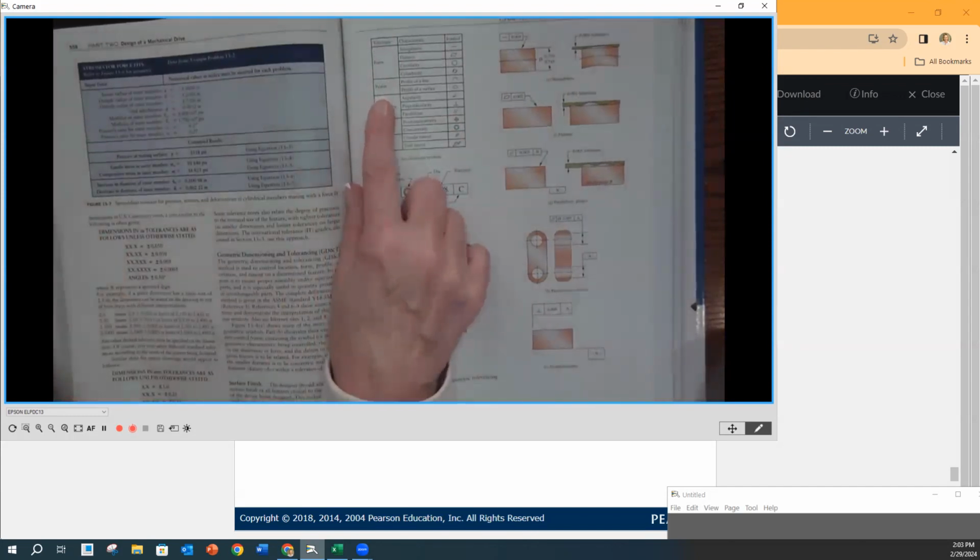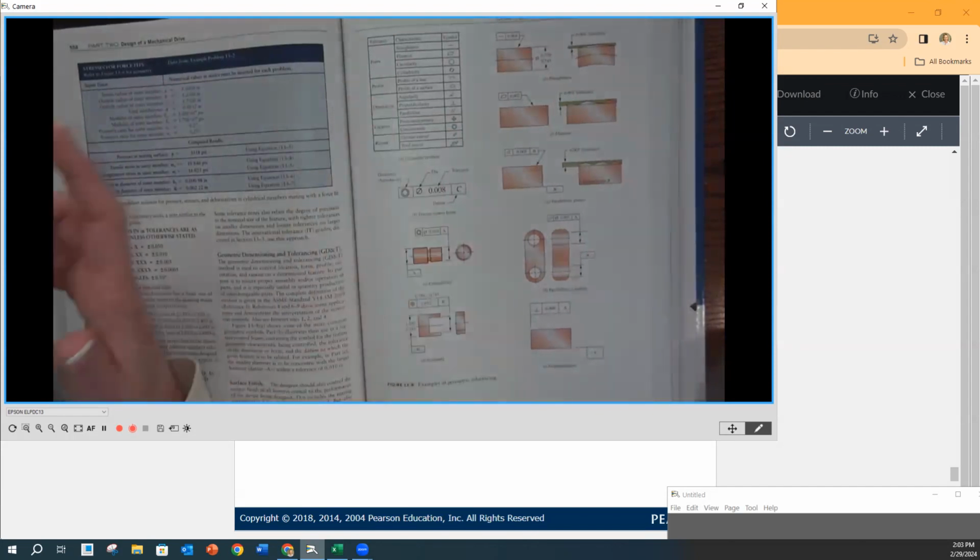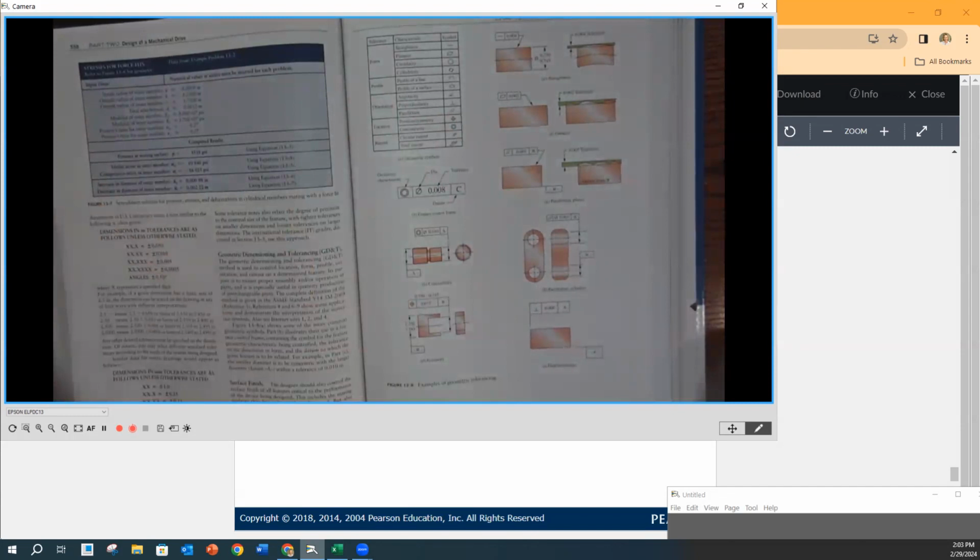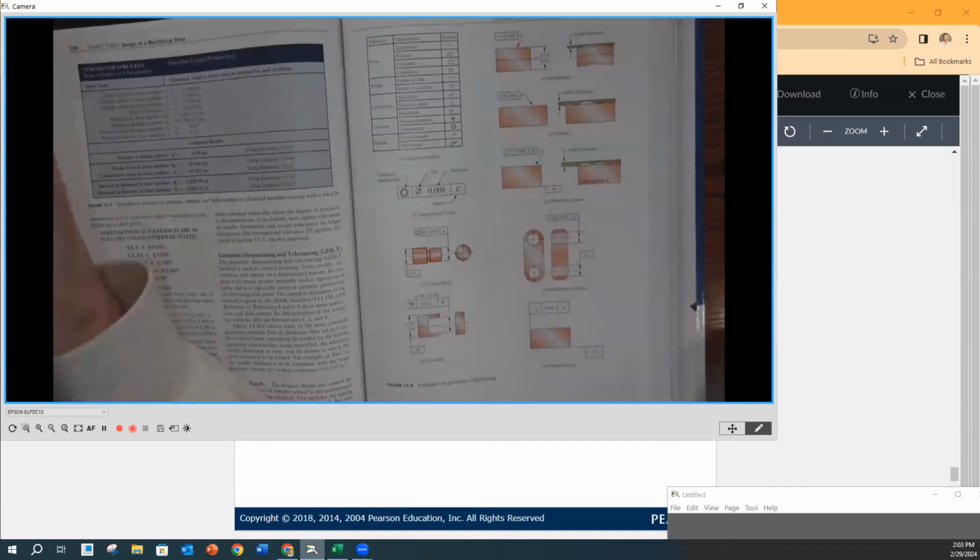Profile, we can control dimensions, really just like our pluses and minuses, locations and size with profile as well. And profile came into the standard early on with one purpose, but it's evolved into something else. Early on it was kind of taking care of things that had a lot of contours and stuff. If you look at your dashboard in your car,